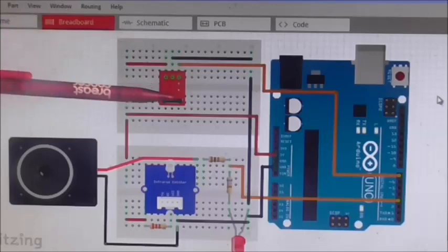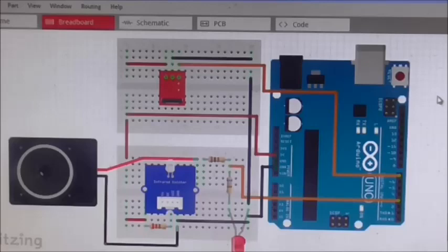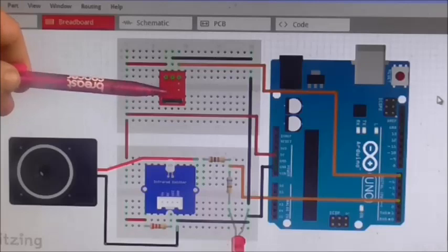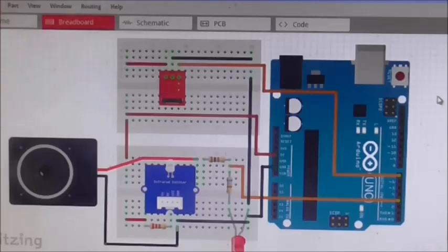On the other side we have a diode which has also been built into a breakout board, and it has some concomitant circuitry. It has automatic gain control and preamplifiers and things like that, and what it does is the diode looks at the infrared, and if there's a signal from infrared it goes active low, and it sends a signal to the microcontroller and other things happen.